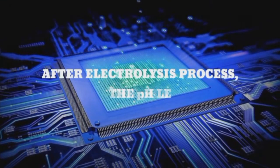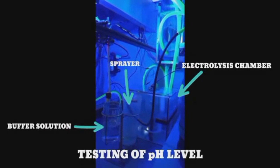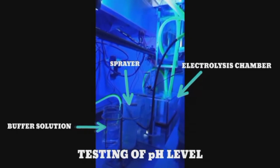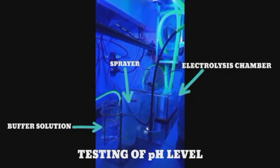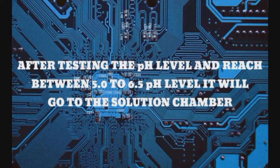After the electrolysis process, the pH level of the solution will be tested using the analog pH meter. The analog pH meter is stored in buffer solution, then it will move to the sprayer where the excess buffer solution will be removed, then it will go to the electrolysis chamber where the pH meter will start to test the pH value of the solution. After the test, the pH meter will go back to the buffer solution. After testing, if the pH level is between 5.0 and 6.5, it will go to the solution chamber.